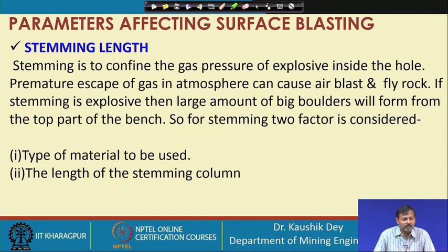Stemming length is basically the part of the hole which is filled with inert material. Stemming is carried out to confine the gas pressure of the explosive inside the hole. Premature escape of the gas into the atmosphere can cause air blast and fly rock, and we need the utilization of that gas pressure for throwing the fragmented rock in the forward direction. So, confinement of the generated gas inside the hole is essential.